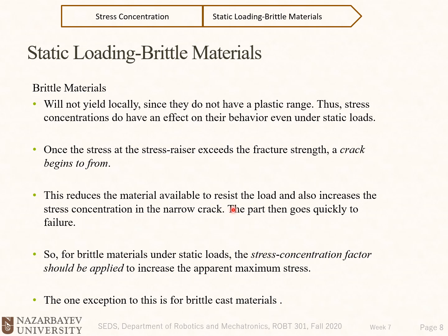So it basically works as a positive feedback loop. Once a crack opens, it develops and grows very quickly, and suddenly the part breaks at the point of stress concentration. So for brittle materials under static load, the stress concentration factor should be applied to increase the apparent maximum stress.